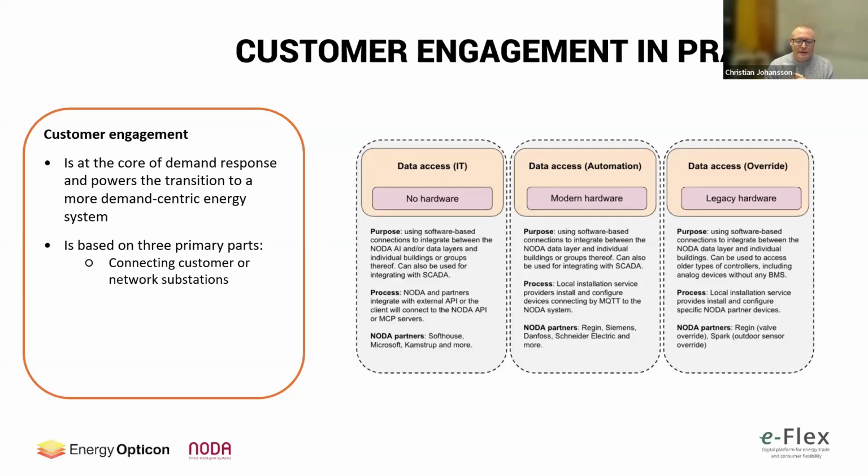And first step, get the data into the system. Here we have the 3 different levels of data access that we're talking about. Obviously you don't want to add more hardware. There are already controllers in all buildings. There are already BMS, building management systems, and sensors in most buildings. If this is the case, well, connect to these things. This is the first step here with the IT based. I think this is really what we're trying to push in these kind of projects.